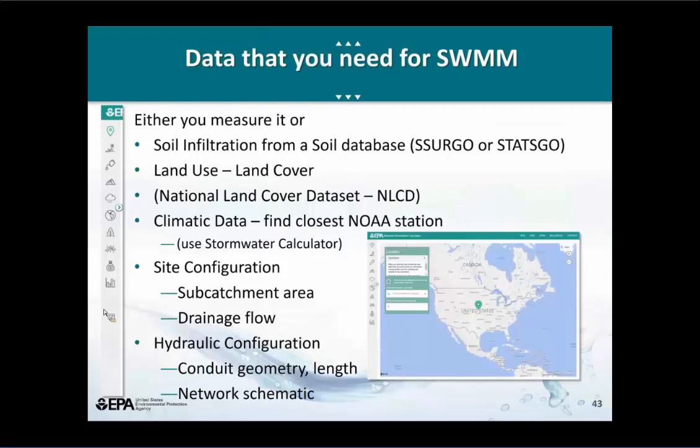We took 100 acres. We put in rain gardens. I have to say, I inherited a project with the retirement of my colleague Richfield, and we had 100 acres. We put in as many rain gardens as we possibly could, and we measured to see how the runoff changed. We measured soil infiltration. We measured rain.